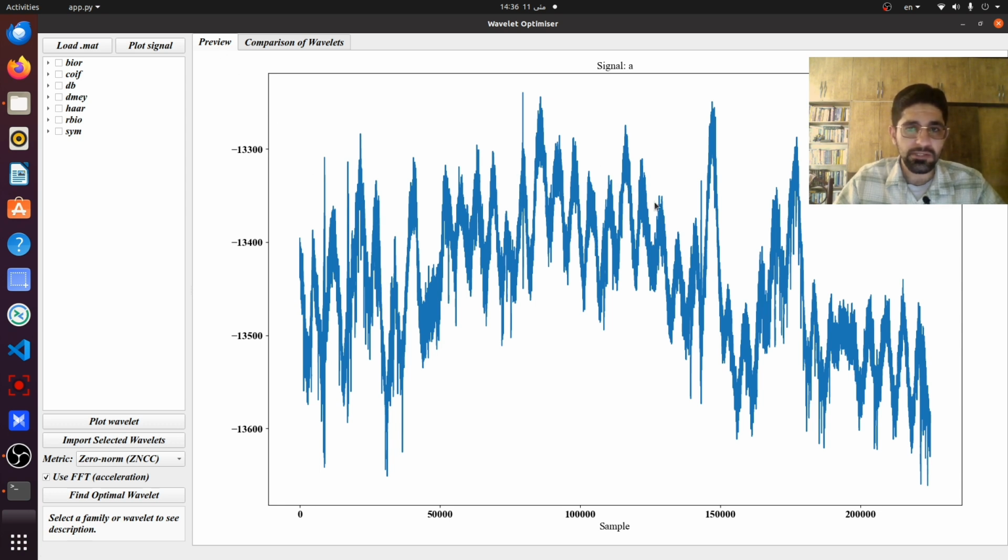And so first of all, what's the use of applying such a process on the signal? What's the use of selecting optimal wavelet among all possible discrete wavelet transforms? The domain-specific signals rarely fit textbook wavelets, and EEG bursts or multielectrode array spike trains, or even details of a speech signal have different time frequency fingerprints.